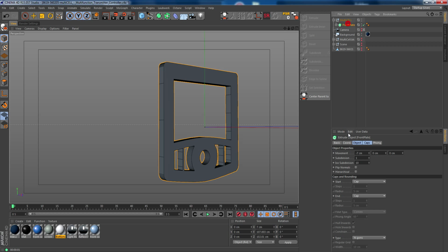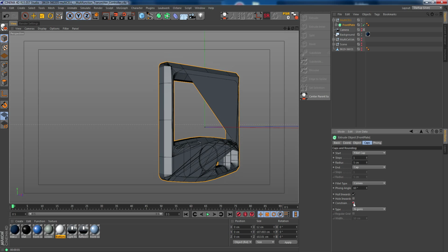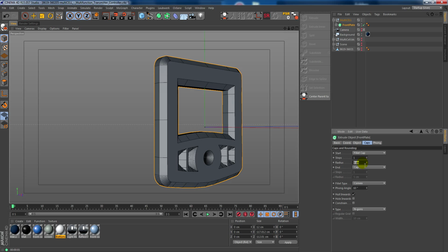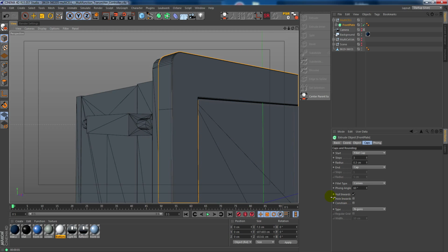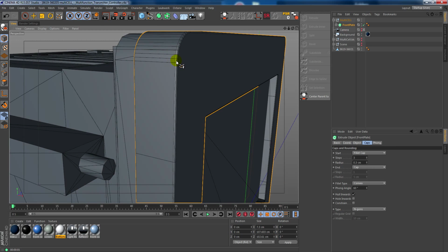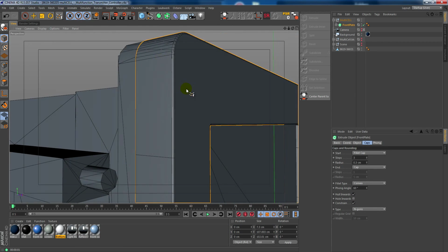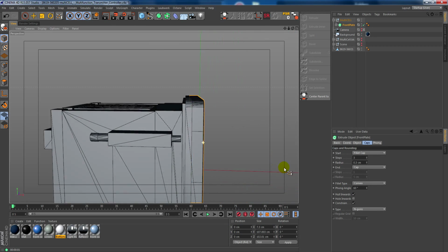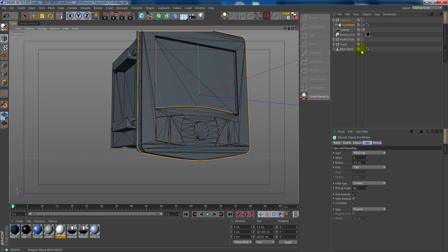Okay, next thing we're going to do is just bevel these edges. Let's give them a cap. And we want to constrain this. So let's give it a 0.3 radius here. And the constrain option will basically, if we just bring our cell back here, when we don't have constrain on, you can see the fillet here will actually expand, whereas if we constrain it, it will keep its original size, which is exactly what we want. And that is the front plate.